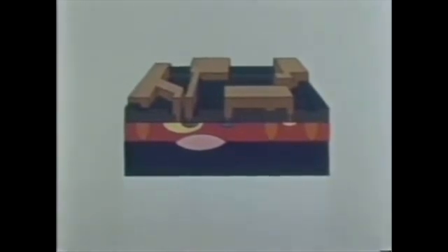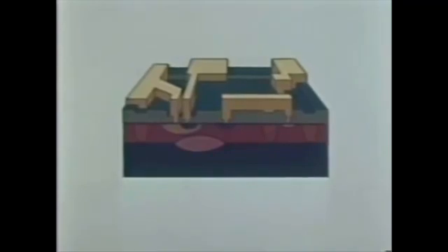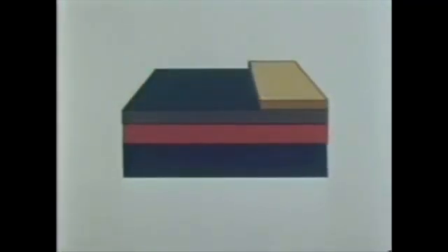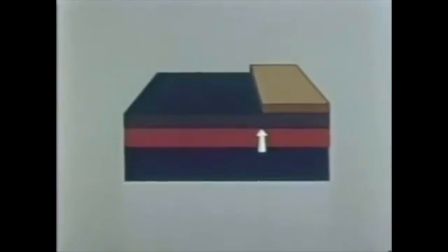Sometimes we like to make resistors a different way, by using the metal interconnection pattern. All you have to do is make the metal pathway a little narrower, and it provides higher resistance. If we wish to make a capacitor, we take advantage of the fact that the oxide layer is an excellent dielectric material. A small area of metal is deposited, forming one plate of a capacitor. The oxide is the dielectric, and the silicon directly below the oxide forms the other plate.